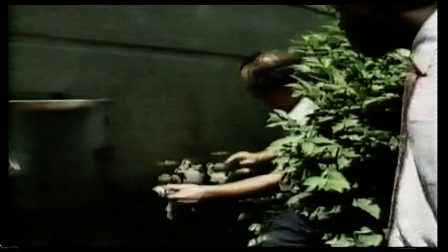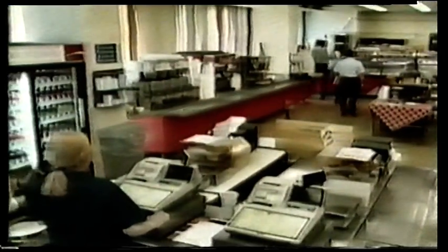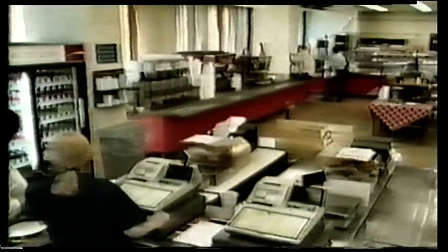In our hospital survey, a reduced pressure principle backflow prevention assembly is installed to provide the highest level of protection, even though chemical additives are not utilized. The above-grade installation allows the assembly to operate properly, avoiding malfunction due to submersion in below-grade installations. Cafeterias and kitchens have many cross-connections, such as ice machines, post-mixed beverage machines, disposals, sanitizing equipment, dishwashers, and hood washers.